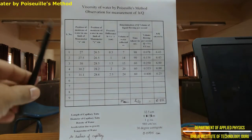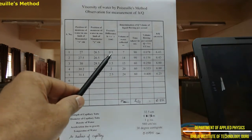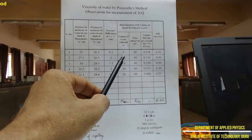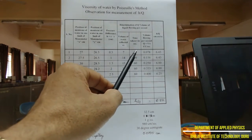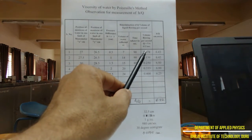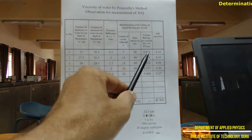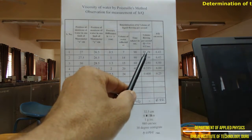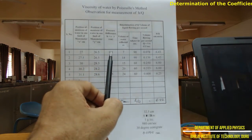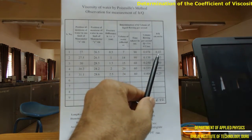Initially, the left arm was kept at 27, right arm at 26.5. So the pressure difference was 0.5 centimeter. Volume collected in the measuring cylinder was 7 ml. Time taken was 90 seconds. So 7 divided by 90 gives us the volume per second, that is 0.078 cubic centimeter per second. Now if I divide h, that is 0.5, by 0.078, what I get is h by q.